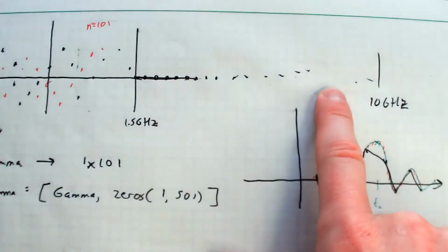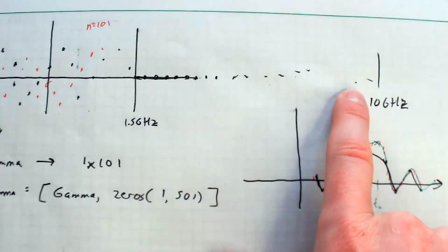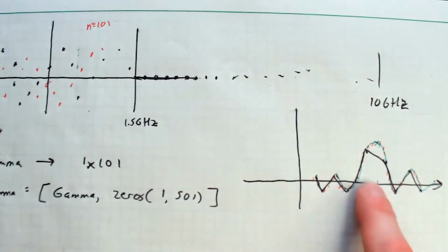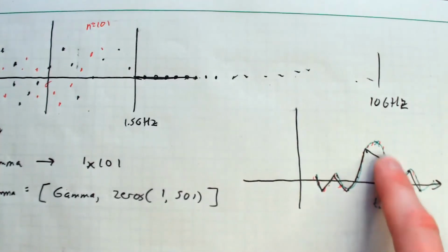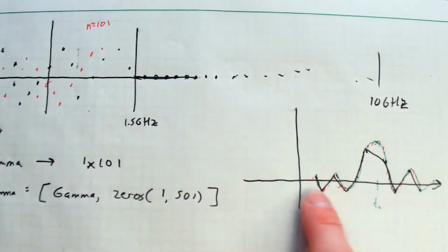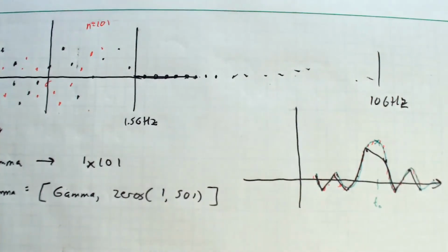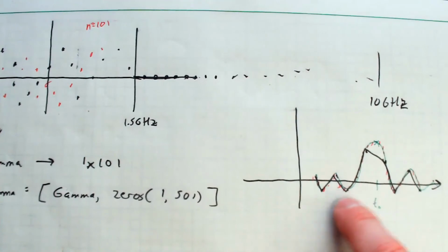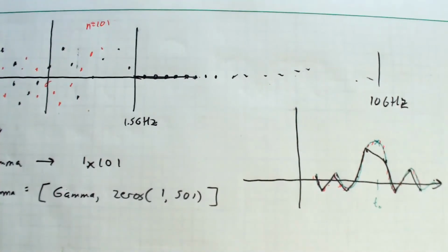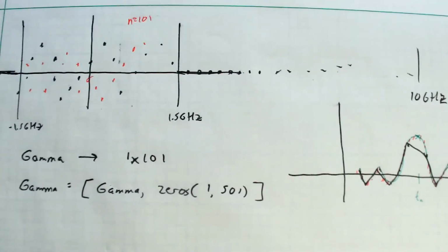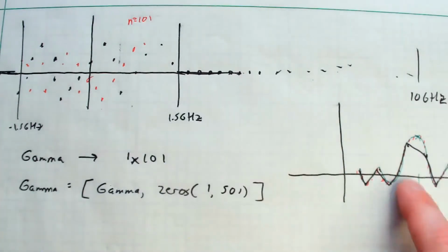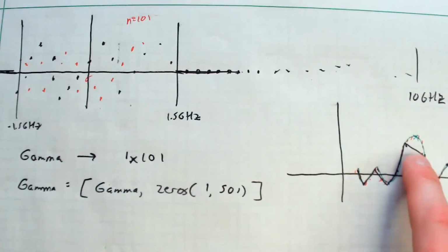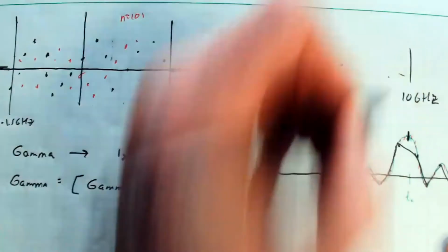But you just are adding it with a bunch of zeros. So it's as if you get that extra bandwidth, but it didn't change the fundamental structure of that little sinc pulse. It just sort of recovered some of the interpolation points between them in a weird sense. So it's a weird little trick where I didn't actually add any information, yet I was able to much better recover where my peak was in that little pulse.